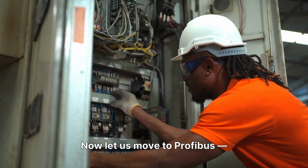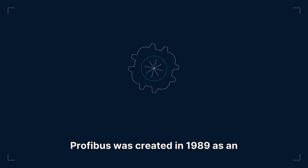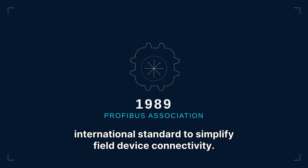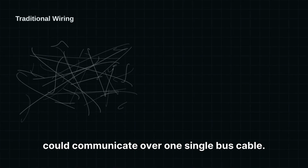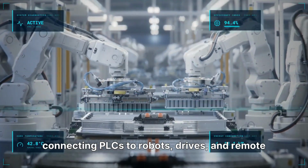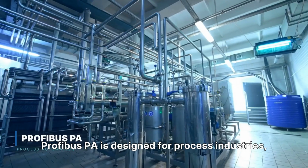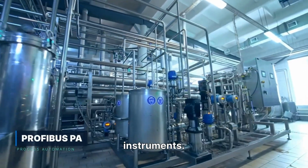Now let us move to Profibus, the fast and reliable field bus for high-speed factories. Profibus was created in 1989 as an international standard to simplify field device connectivity. Instead of hundreds of wires, many devices could communicate over one single bus cable. Profibus DP is used in factory automation, connecting PLCs to robots, drives, and remote I/O. Profibus PA is designed for process industries, carrying both power and data to field instruments.